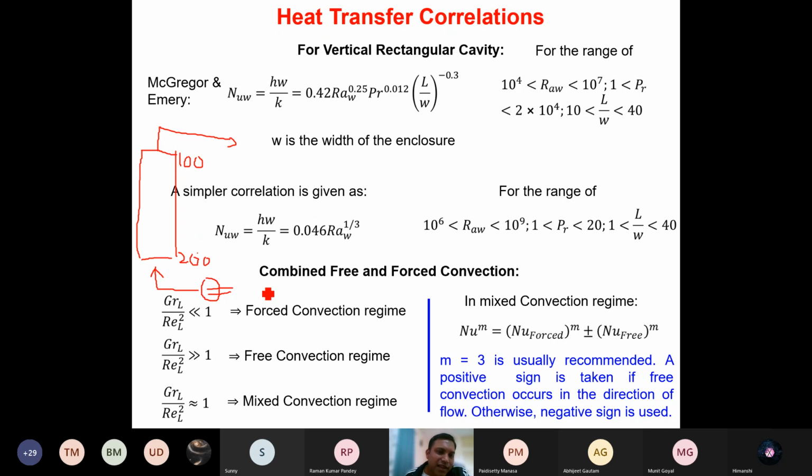So not only is there a movement of the particle because of the mechanical element in the upward direction, but also this density difference because of the temperature difference will be active here. Do you all agree or not? Does it make sense what I'm saying? Hello? Yes, sir. So both the factors are going to be there, but which correlation should you use?